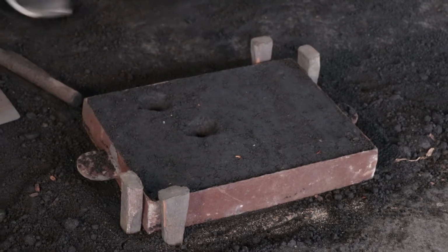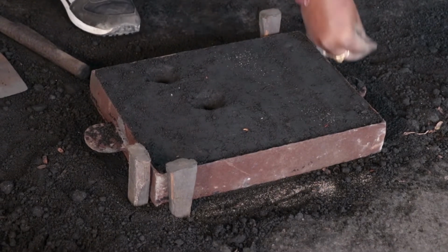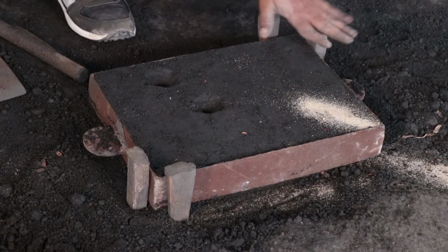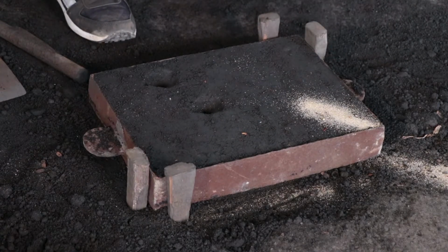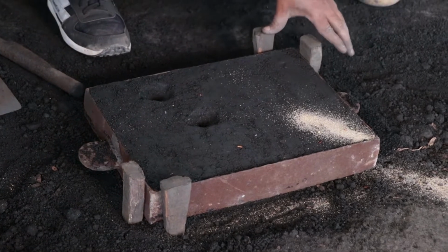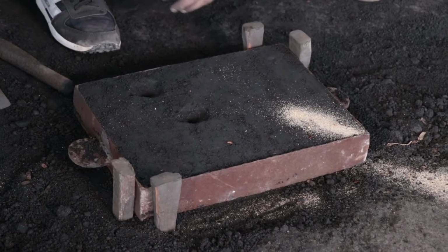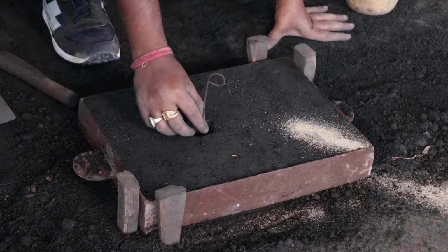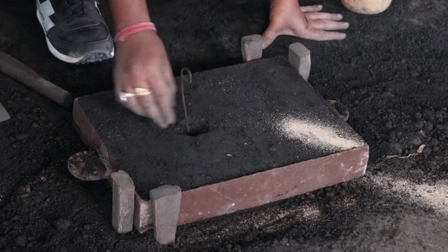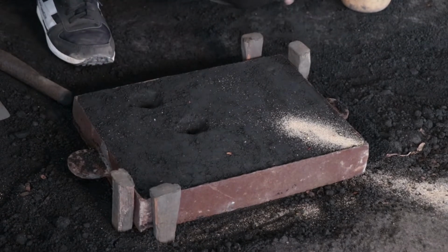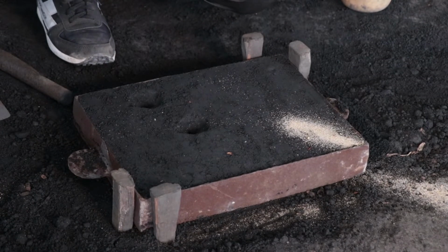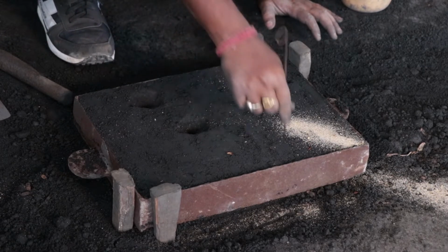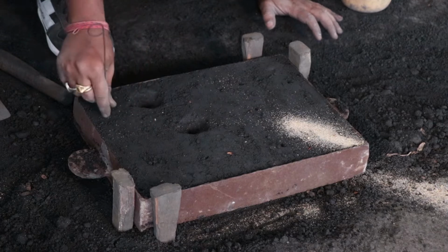After this, with the same parting sand, we are just giving a mark over here so that we can remember that this is the place. This is your venting rod. Leave the venting rod in the entire hole because both are of the same size. Take the entire size of the hole. For 1/3, you need to do a venting over here so that hot air and gas will come out easily from this.